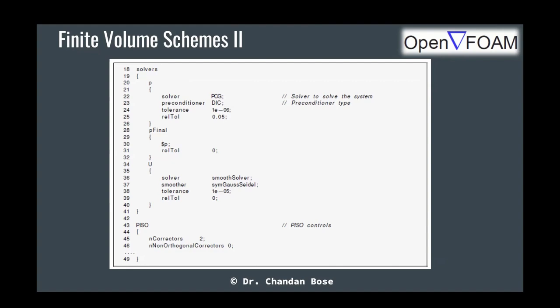So the loading time, which is taking a lot of the time, is like 5 minutes, sometimes like 10 minutes. Is there anything related to this? There is an additional functionality called foamToVTK. It is a post-processing function which will directly convert all your OpenFOAM data into VTK format. If you are using Tecplot, converting it to VTK format first makes sense because Tecplot can quickly read VTK files.